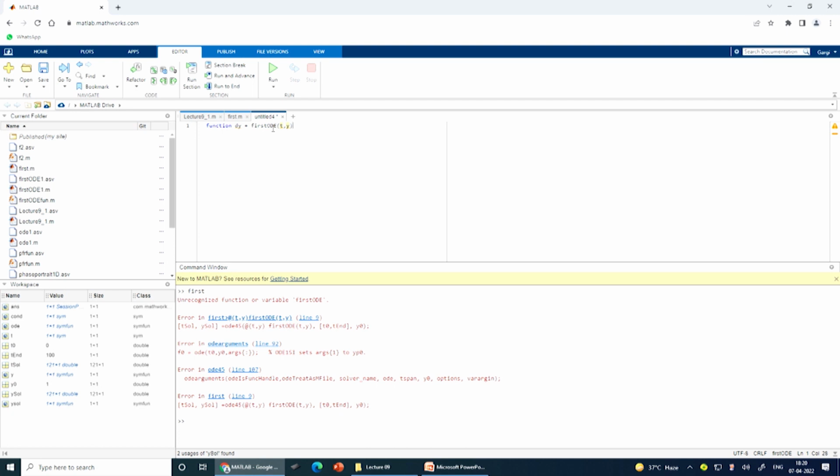On the next line, define dy, the function dy. So dy, we are talking about a logistic growth. So let's write a logistic growth here, 0.8 y minus 0.08 y square. Notice that I have used numbers instead of variables. You can also use constants like r instead of 0.8. But since this is the first time that we are covering MATLAB, let's look at the simple options here.